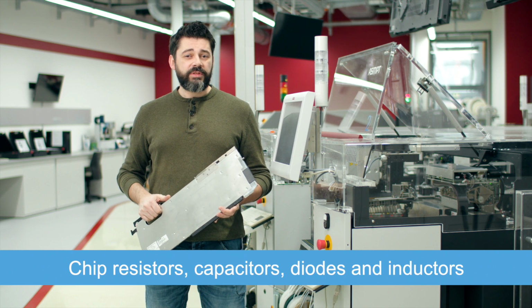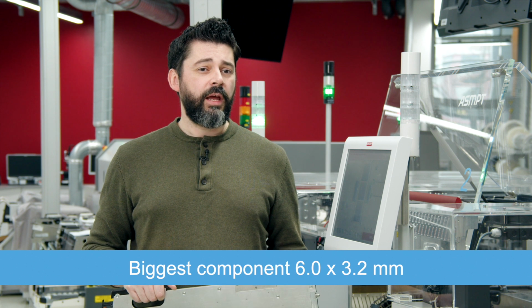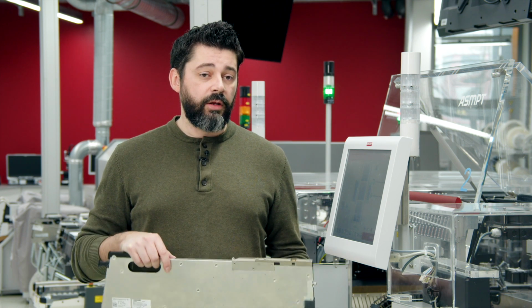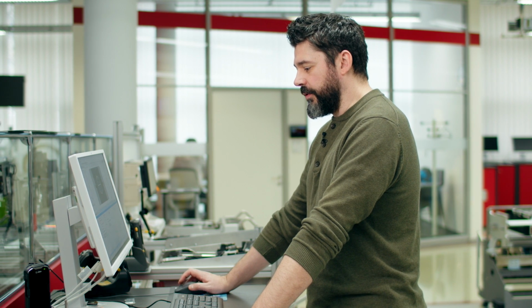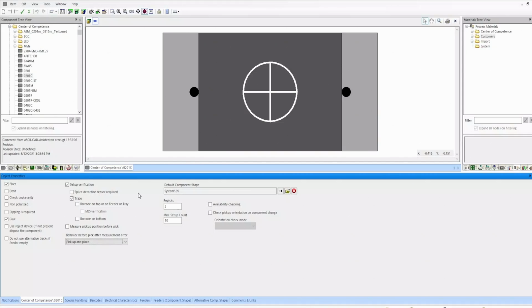And the maximum size of the component itself can be 6 by 3.2 millimeter, and the minimum size is 0201 inch. And all this functionality within an 8 millimeter feeder. So now we are here on the SIPLACE Pro Desk to program or specify the component itself. We have here an open component, an 0201 C chip. Standard-wise, everything is set up.